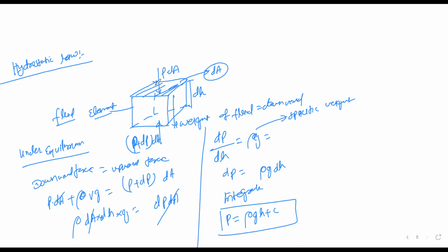So let's assume this is the free surface of water and the whole body is submerged. If the height of any body is 0, it means that body will have atmospheric pressure. Remember always, when the height becomes 0, the pressure will be atmospheric pressure. Any body is always in contact with atmospheric pressure.